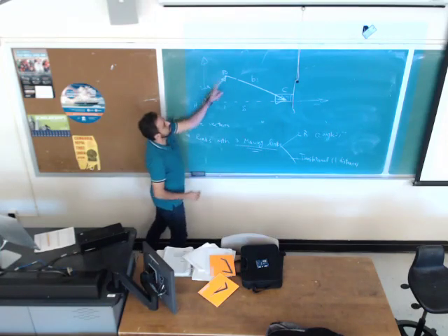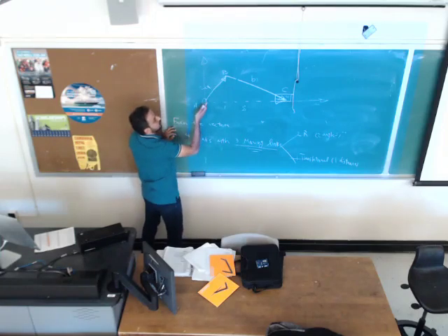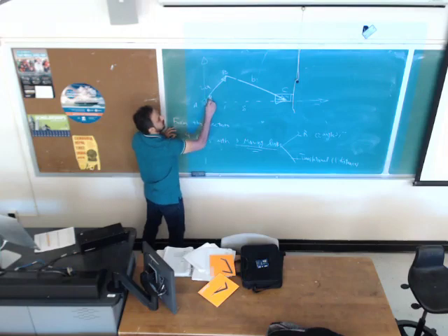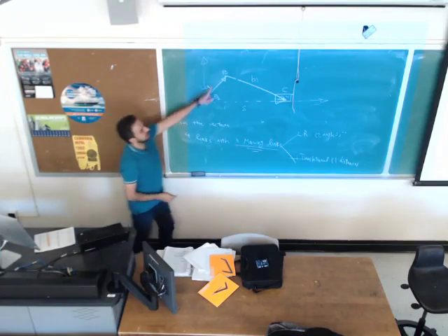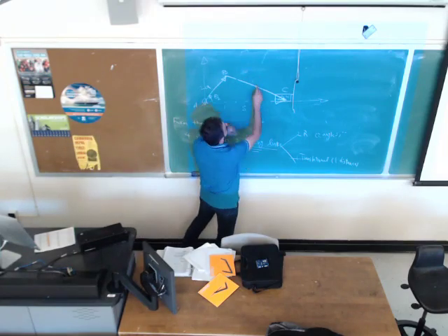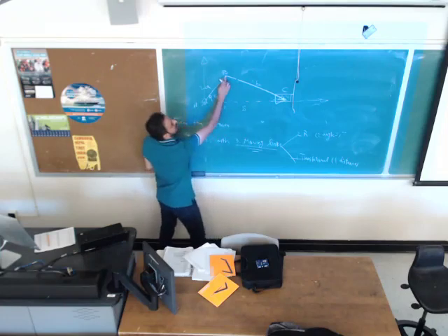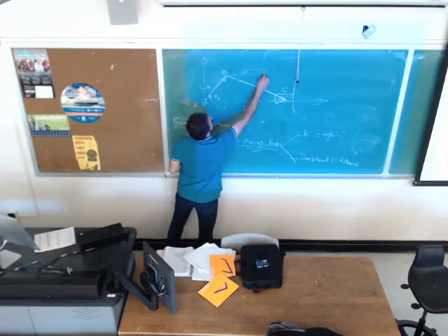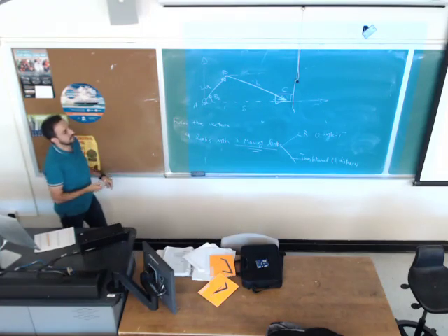Link 2, the angle of link 2 with the ground should be measured at point A, the starting point. Going from ground, go all the way counterclockwise, labeled theta 2. Link 3, the angle should be measured at point B because B is a starting point.